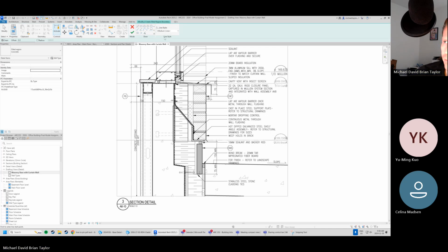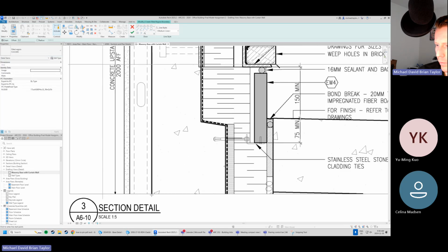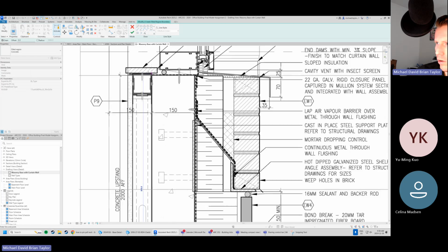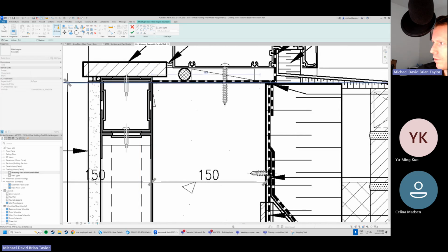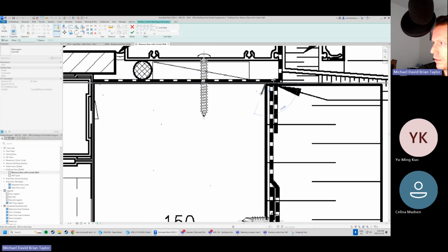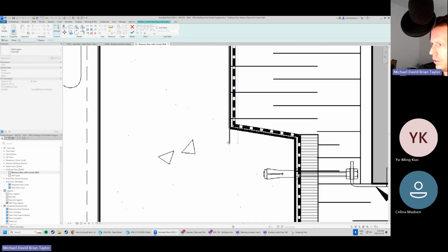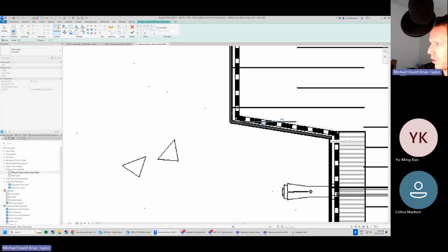I'm still inside of the filled region tool here. So I've got concrete, filled region. I'm going to go ahead and trace this dimension here. Let's trace this out. I can see that I've got 150, so I'm really going to do my best. You can see how 150 there is populating. Looking good. Got a little piece here. I'm going to trace this out.